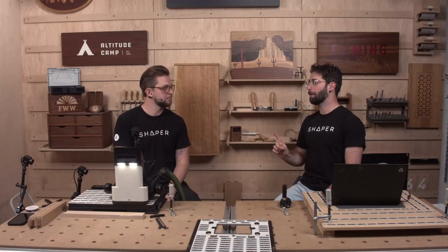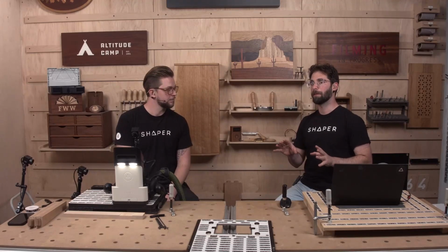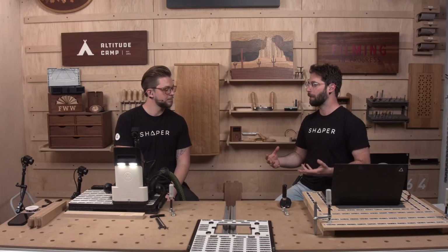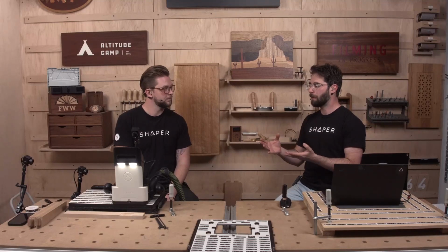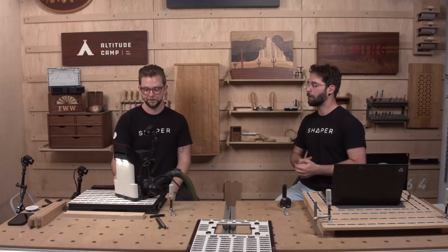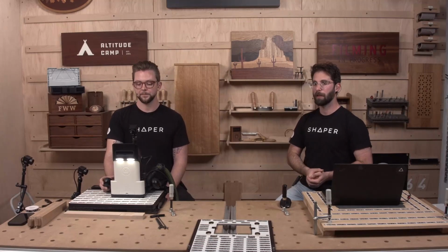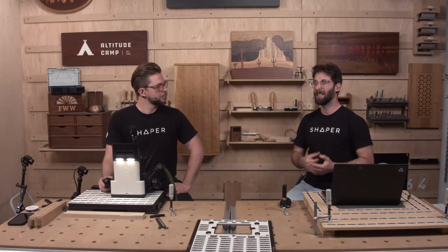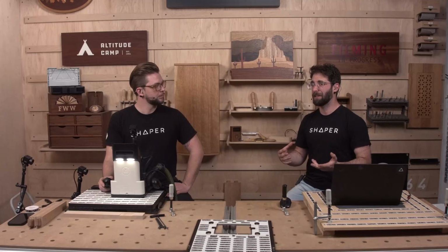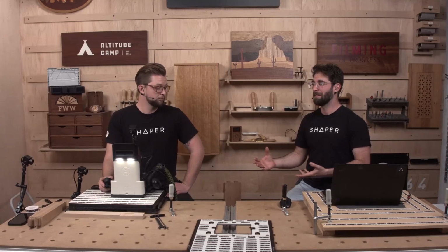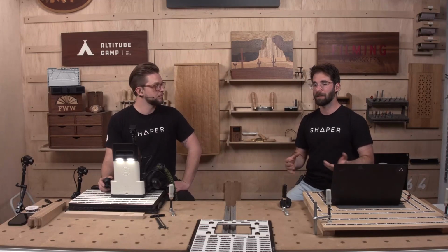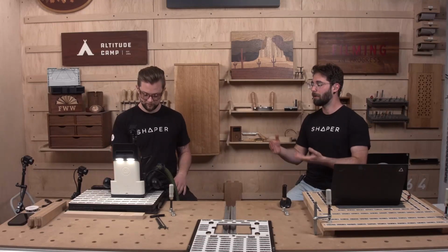I do have one thing that we kind of glossed over and that I think a lot of people here will identify with. For editing, not just encoding, but editing encoded depths on Tool. Why do we do this? It's because you don't always want to have to go back to the computer. If you made a little mistake in Studio or in Fusion 360, you want to be able to fix it on Tool.